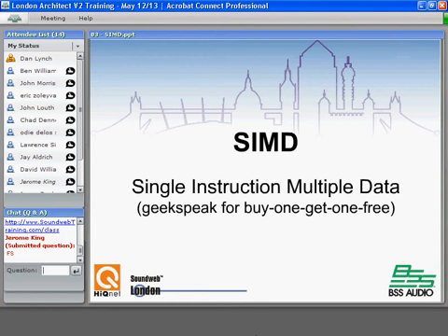It requires a lot more work on the programmer's part to create processing objects, but you end up with these special SIMD processing objects which are able to run two streams of digital audio through the chip at the same time, truly simultaneously, as long as they're both getting the same mathematical function performed on them, same mathematical operator. They can run simultaneously on the same clock cycle. It's a big deal. Very big deal.